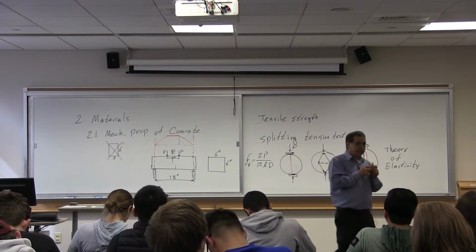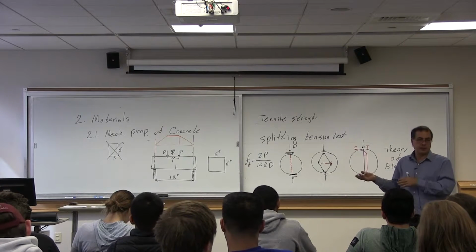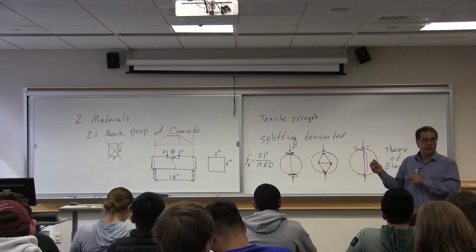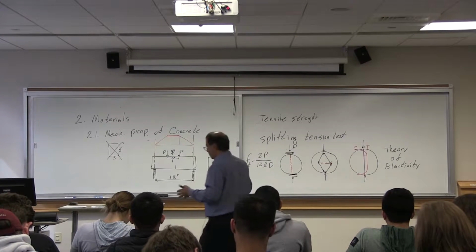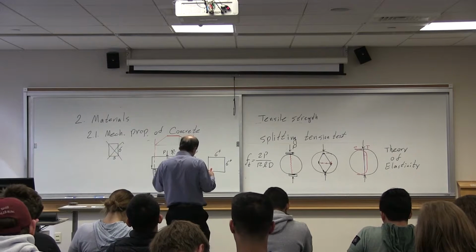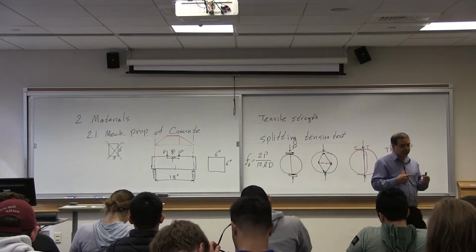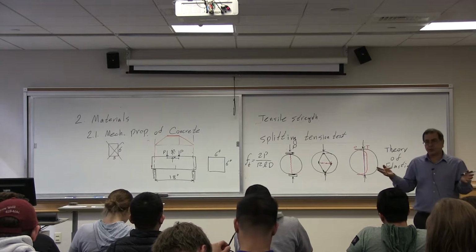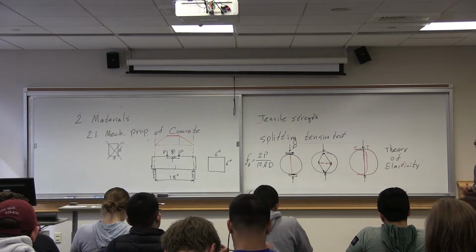Usually we say that if the specimen didn't break between the two loads, we disregard the test, so we run the test again. We did, a few years ago, maybe 6 of these tests. One of them broke outside the range. The other 5 cracked in between.